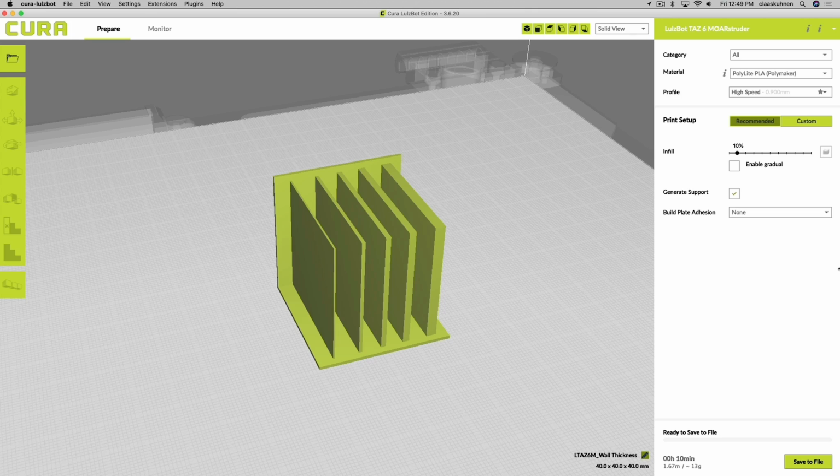Let's take a look at wall thickness in general. So far we covered support, infill, the orientation, material, and the next one that is very important to be aware of is wall thickness. I have various test walls here from 0.5 to bigger thicknesses. I use a Mora extruder. It has a 1.2 millimeter wide printing head attached. So let's see how I can print this.